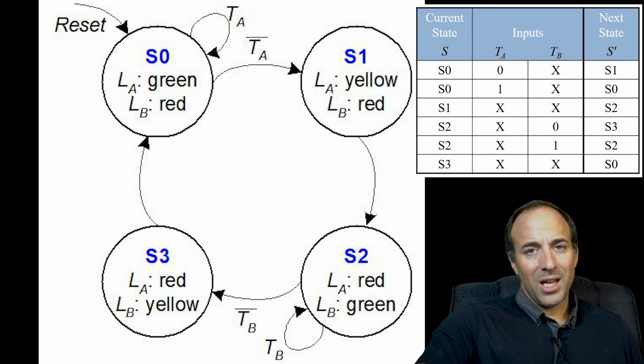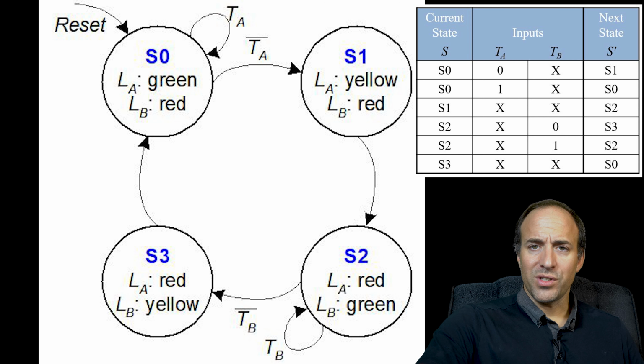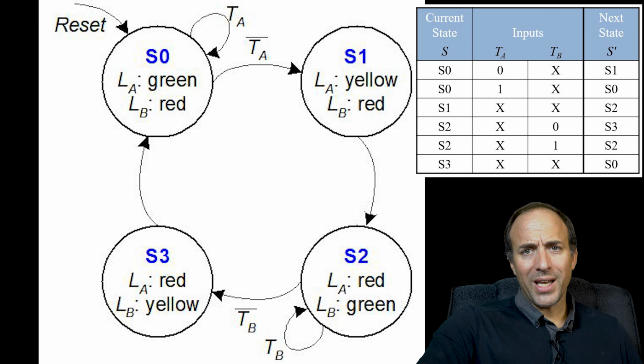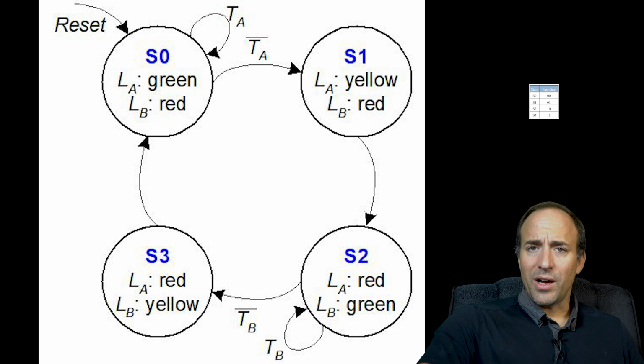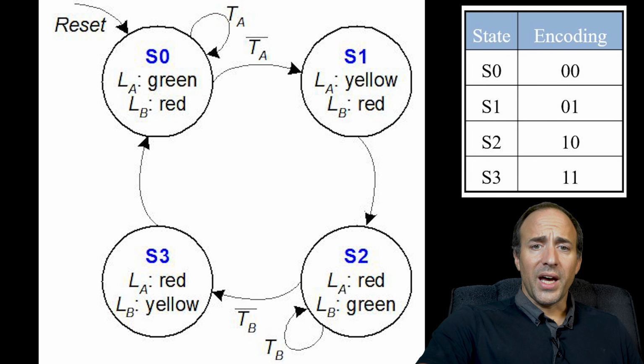As a matter of fact, in many cases, designers like to use 1 state bit per state so they can use one-hot encoding, meaning that every state value has one 1 bit and the rest 0 bits. But in our case, we'll use a simple binary assignment of the states. So we'll associate the values 00, 01, 10, and 11 for S0, S1, S2, and S3 respectively. The only state code that we can't change is the start state, which always must be zeros.